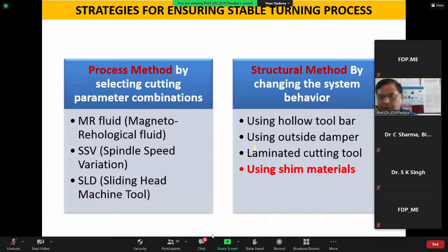We change the spindle speed with the gearbox in our manual lathe machine. So that spindle speed remains constant until you change the gear during the operation. But your cutting speed is going to change. Why? Because during the cutting operation, as you are taking a number of depths of cut, the effective diameter is going to reduce step by step.